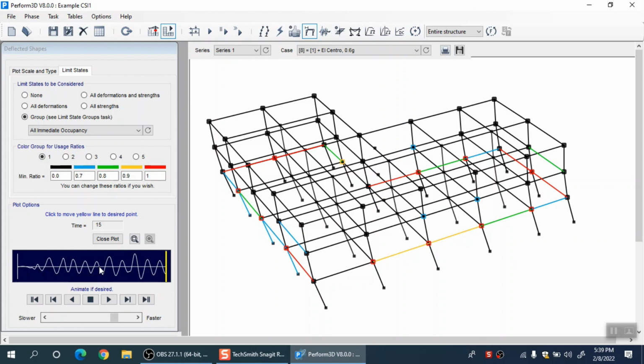you can maybe tolerate that, right. So, in PBD it is not that if a DC ratio exceeds 1, it is gone. You will see the structure as a whole. For example, if there are 500 beams in a high rise building, how many are exceeding, for example, IO at a certain level. It is not that one beam exceeds a particular performance level and then you will change the design, right. So, those are actually practical issues which you are referring to.